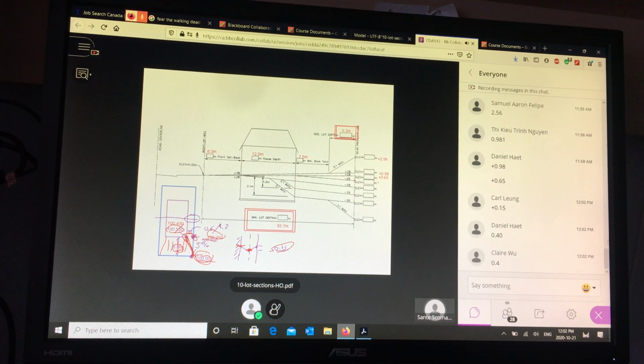Okay, Daniel and Claire, I think if you're off there, let's do it again. If you have to do the calculation in 2 parts, you can. So what's the elevation at the back of the building? The elevation here is going to be 20 times 0.02 is 0.4, positive. That's the elevation at the back, and then from there we're going to come down at 2%.